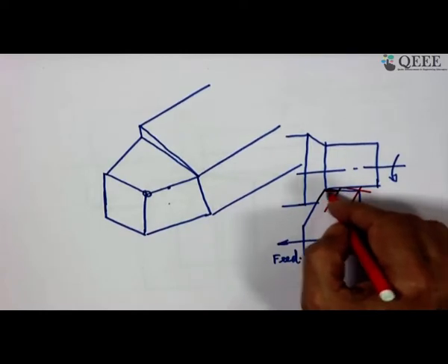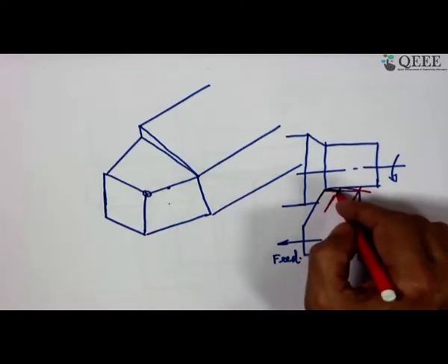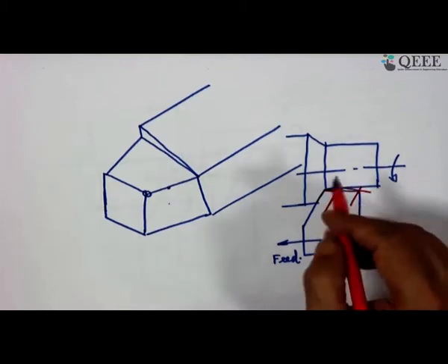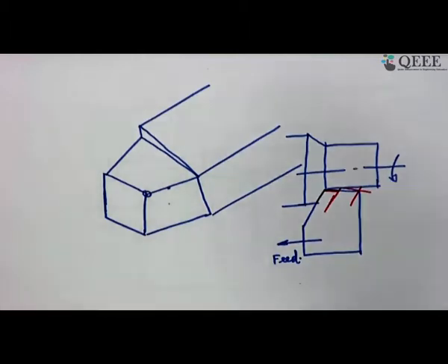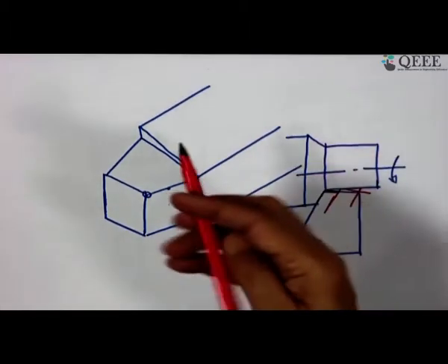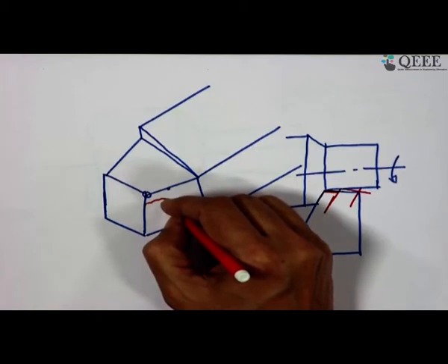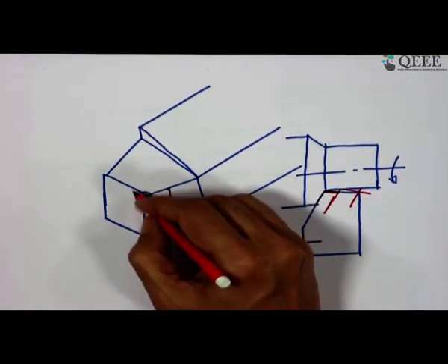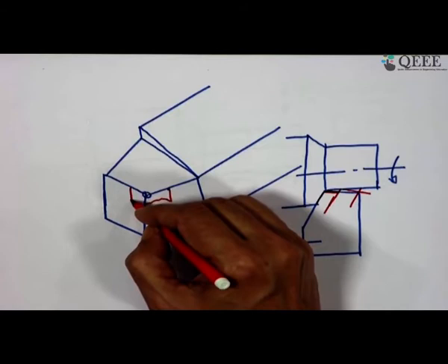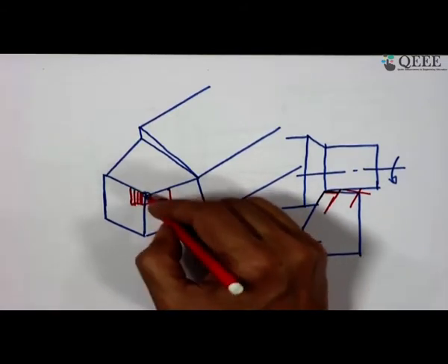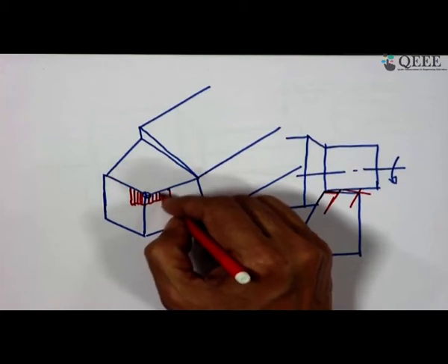Auxiliary flank, this part of the auxiliary cutting edge is engaged in cutting. So, you have also rubbing action over this auxiliary flank, and as a result we may expect that here you have rubbing action and you have a rubbing mark. So, wear will take place something like this, and wear may also take place like this on this side. So, this will be the wear on the auxiliary side, and you have a wear on the principal side.